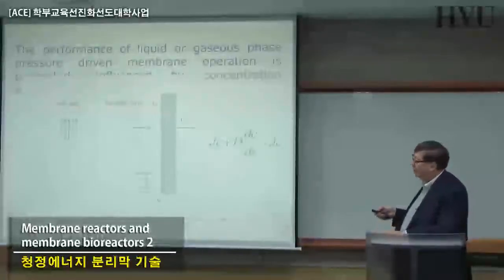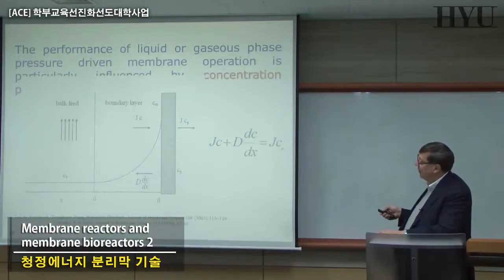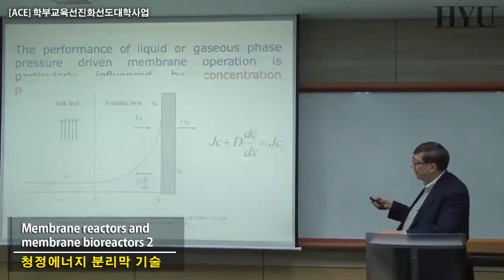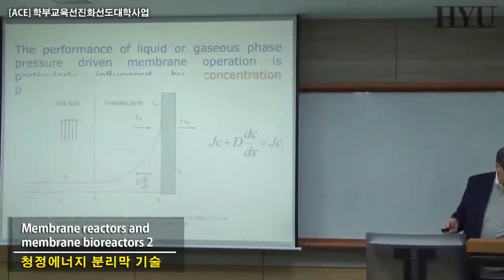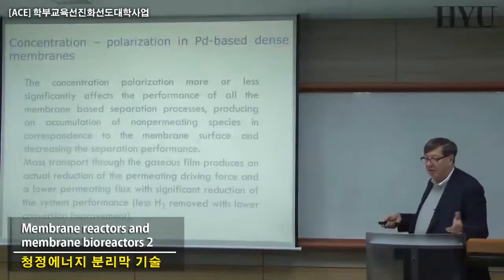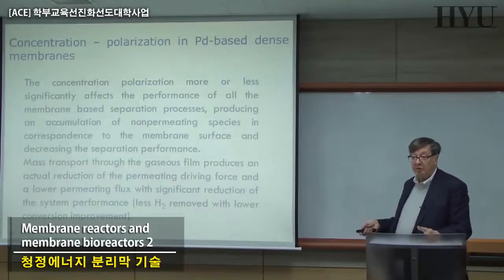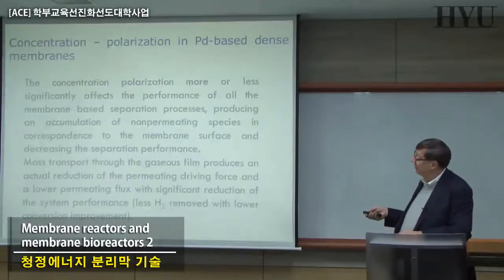and everything is uniform in this stagnation layer, the boundary layer. So we have to integrate between C membrane and C bulk, basically, and there is a difference in this interval, so you have this convective flux, back diffusion, equal to what is going across your membranes. That's the differential equation coming from this film theory, and it is exactly the same equation that we can use in reverse osmosis, in ultrafiltration, and in the palladium membrane that we are discussing.